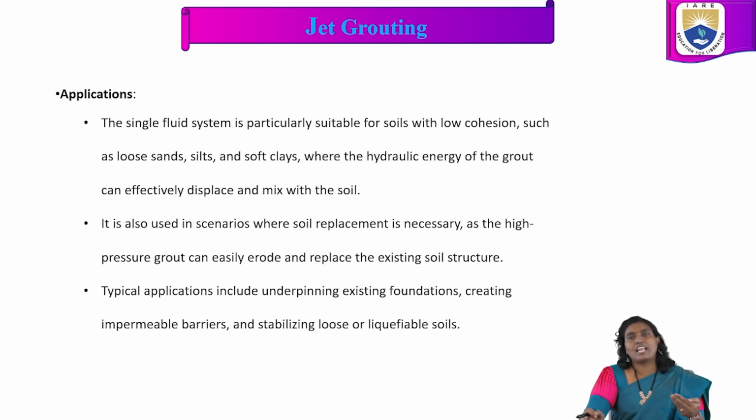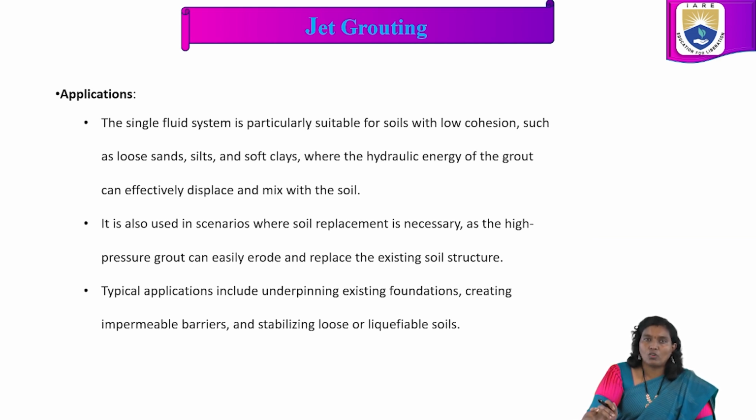In such scenarios we are going to use this. We apply the single fluid system of jet grouting. Typical applications include underpinning existing foundations, creating impermeable barriers, and stabilizing loose or liquefiable soils. So in these cases, we are using the single fluid system of jet grouting.